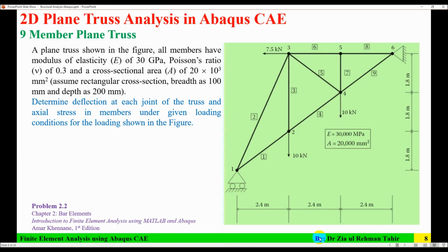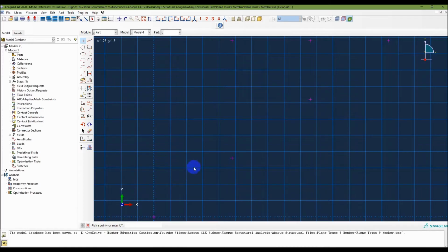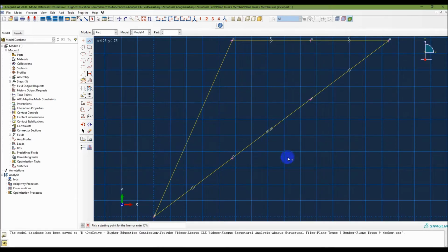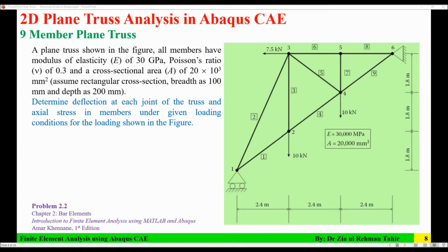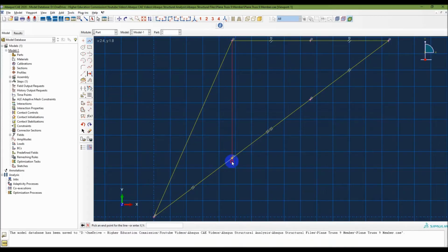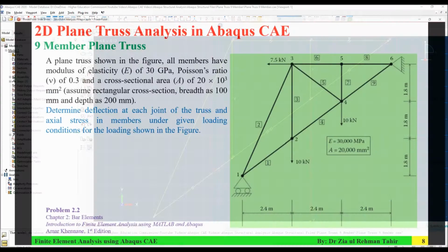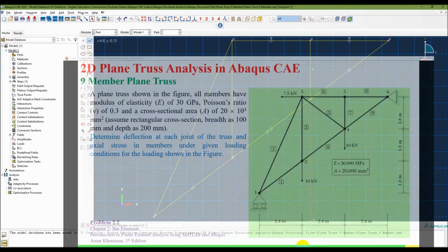Now those 6 points are created here. Next, I'll select Create Lines: Connected and connect these points. Here you go. Then the vertical members here, cancel procedure, again a vertical member there, and then there are some diagonal members joining 3 and 4.